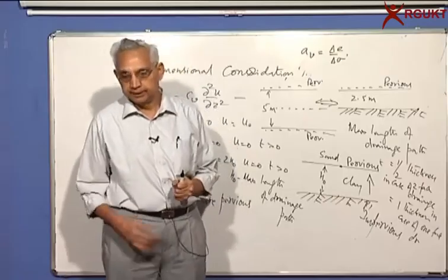The next class. Let's review the phenomenon of consolidation. You have a soil which is saturated with water, and these are all the soil grains. If I just separate out, this is the solid volume, this is the fluid volume. When you apply any stress, nothing will change in terms of volume of the solids, because solids are all incompressible. It can only compress if you allow the water to go out.